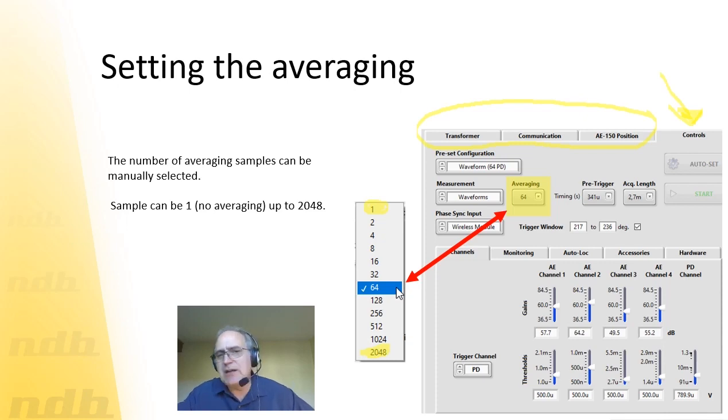And what I do recommend is to start between 64 and 256. This section here is a good trade-off between not having to wait long and being able to see things. So you can start at 128 and see if it's good enough, and if it's not enough, crank it up. Don't start at 2048, because you may wait too long for nothing, because you may realize at the end that this was not something you were looking for. So the suggestion is to start at 256.